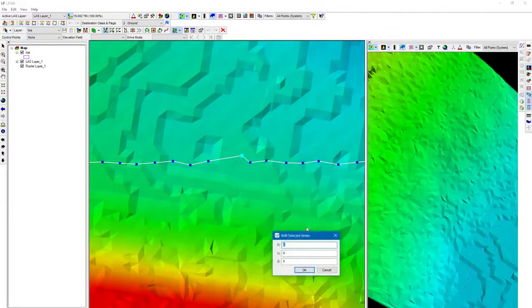You can shift it in a direction. So let's say I wanted to drop the toe of this stockpile down 6 inches, something like that. I knew that the actual base of the stockpile was lower than the point cloud surface that I'm seeing, so I could come in here and say -6, and it's going to drop it 6 inches. We'll just say half a foot. How about that? So -0.5, then we'll drop it half a foot.